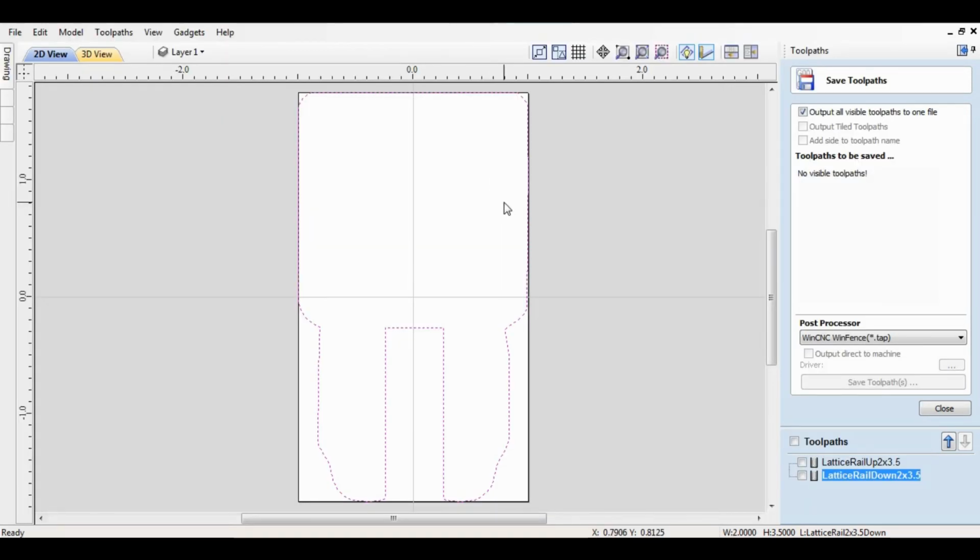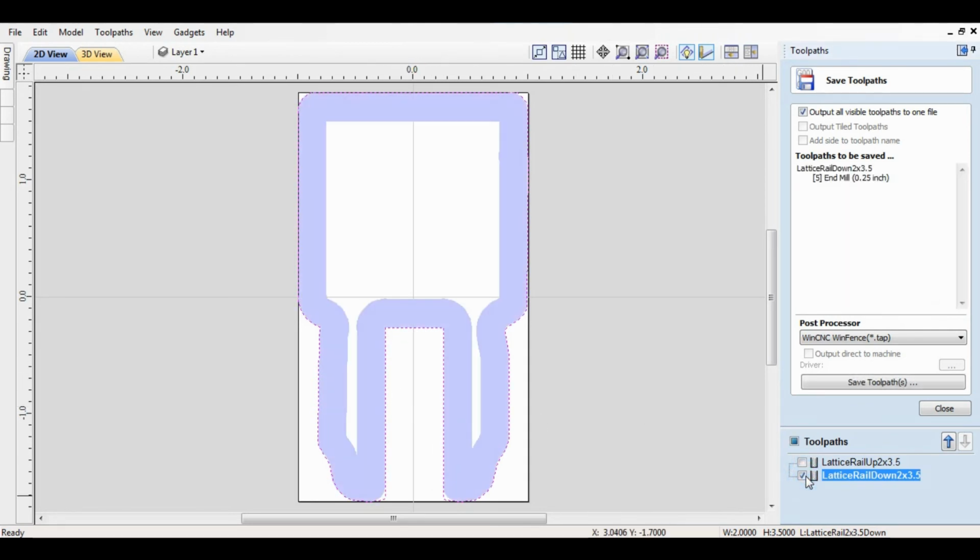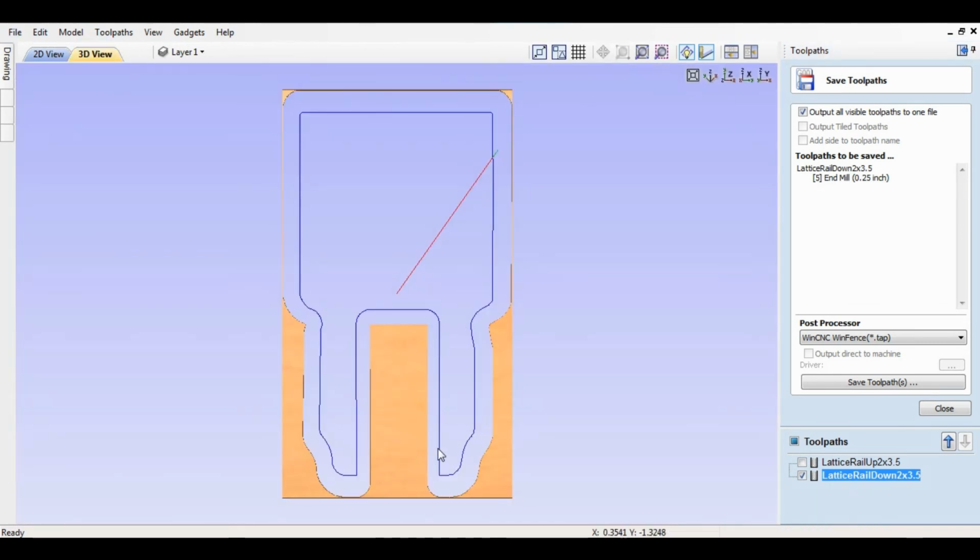Hi, Mike at WinCNC here again, and after I did this video, I thought about something that would probably make this particular hole work a lot better. I noticed that this little tongue that was sticking down in here, and if I click this, you'll see what I'm talking about. Go over to here and look at it. This would probably snap off. I don't know that for sure, but more than likely it would snap off while you're cutting the post and make a jagged hole here at the edge.